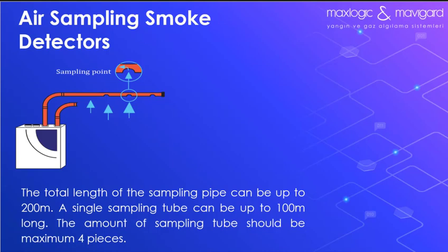And what about 6.5.2.2 in the smoke detector standard? For aspirating smoke detectors, the sampling openings are considered to be equivalent to a point detector.